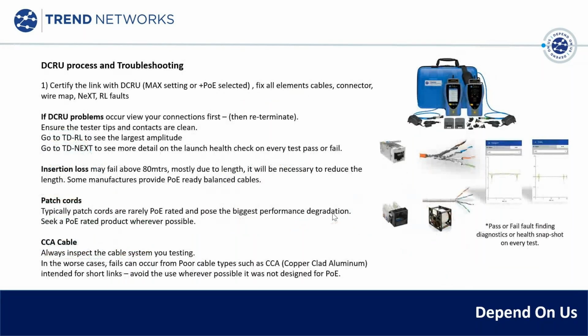So troubleshooting, if we're looking at troubleshooting, there's a few tips just on screen. So of course we'd always certify. We need to certify first. If we certify, I've just put a bunch of things on the screen, and the idea is we can go to our certifier and we can start picking up some of the diagnostics to find which end is the problem. In some cases, insertion loss, where we install cables over 80 meters, because we typically expect cables should work at 90 meters, it may be a problem for us, depending on the type of cable. And so insertion loss can play a problem.